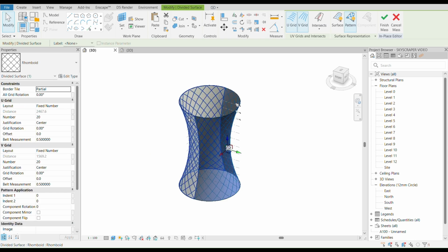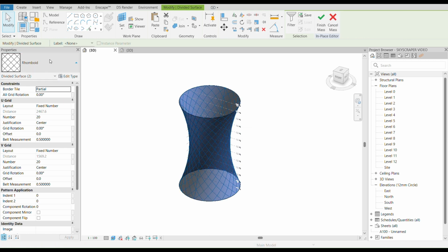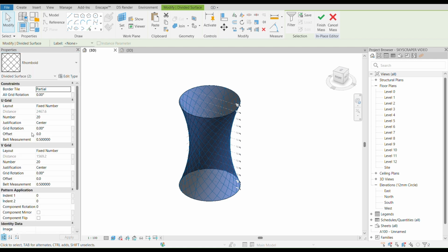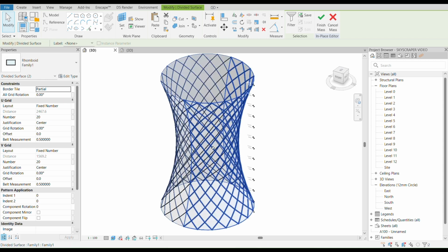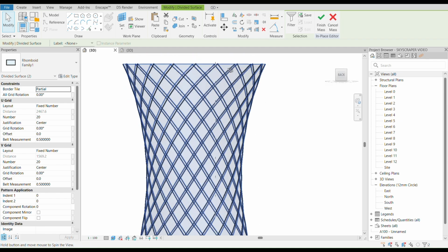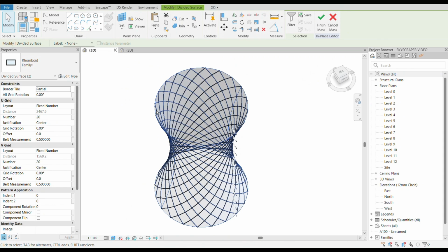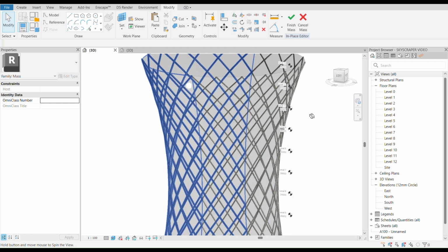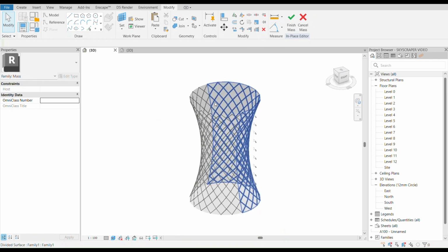Now I'm going to select my tower again, select the two faces, and select the family that I just made. It's this one, family one. I'm gonna wait till it loads in. It usually takes a few seconds, and if you are having any problems when it loads in, like some panels are placed weirdly or some things are happening, it's because your way of creating the pattern was too much for Revit to place it smoothly, and the elements were not actually in harmony. So this looks pretty good. I think it's a good type of a tornado tower example.